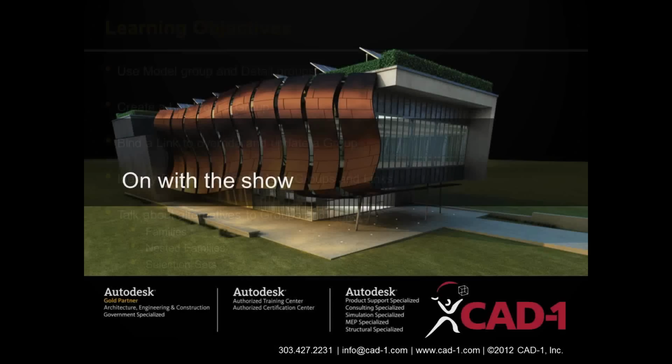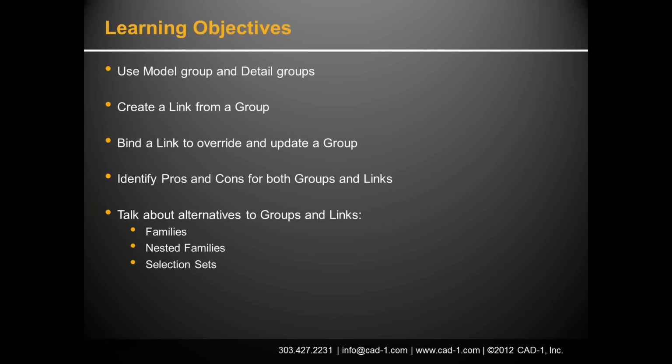So in here we looked at using the model groups, the detailed groups within our project, which is great. We could put those in there, and then after we've gotten our workflow down, we've got the project all together, we'll go out and create a link from that group. Then we can manage it separately, and when we're done with that, we can then bind the link back in to update the group, or we can make the group and create a link from it and go back and forth and constantly change the groups and the links. But at some point, we got to commit to what we're going to do with these.